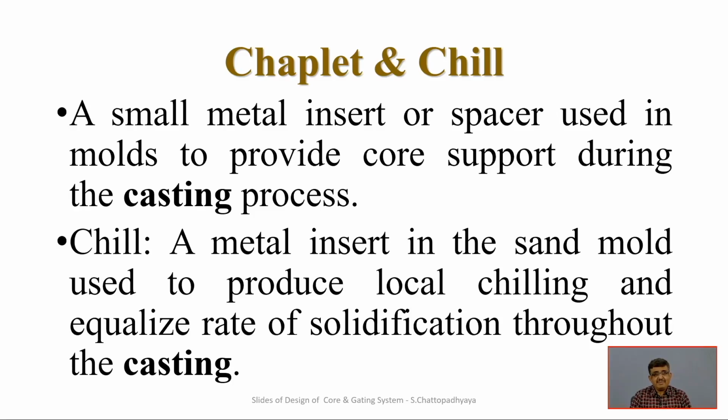And what is a chill? A metal insert in the sand mold used to produce local chilling and equalize the rate of solidification through the casting. So, the cooling process is very, very important. The faster you cool, the smaller the grain size is, and the smaller the grain, the higher the strength. So, one has to provide some kind of directional solidification, directional cooling, and some metal inserts can ensure those directional chills at appropriate places, so that hot tears and other kinds of cracks will not be there.